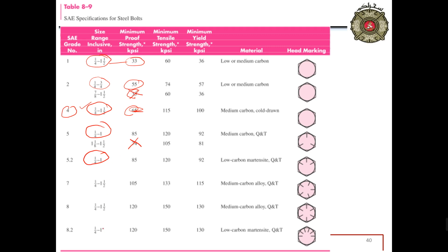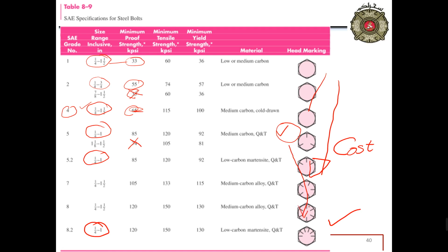The best method from a student's point of view is to select the strongest bolt, and it will always hold the applied load, but it is not a correct method because, let's say, the cost of the bolt is increasing downward. Let's say you have chosen this bolt, and this bolt was sufficient to hold the applied load, then this difference in cost will be added for each bolt that you have added in the system.